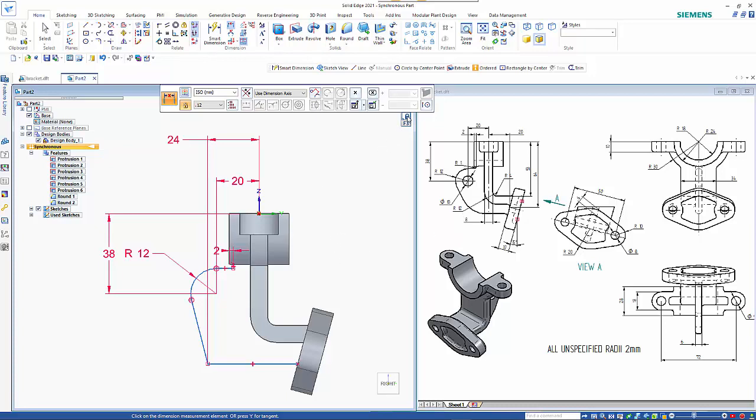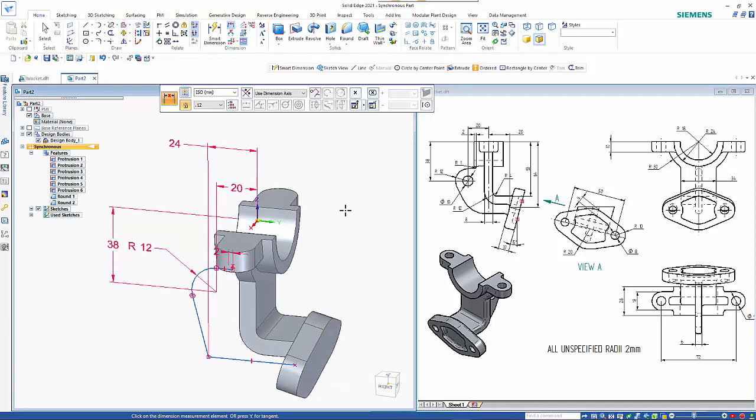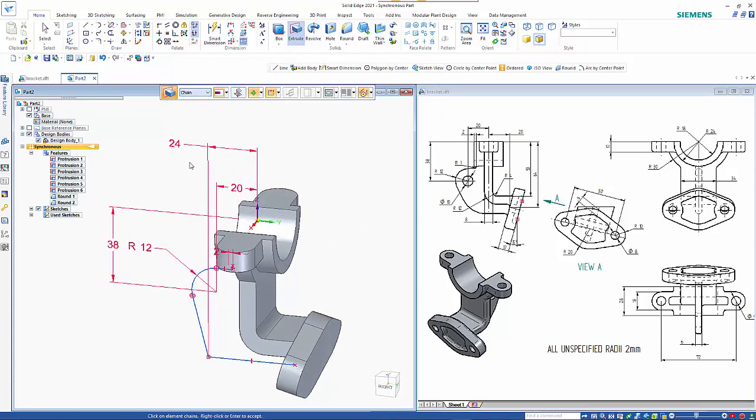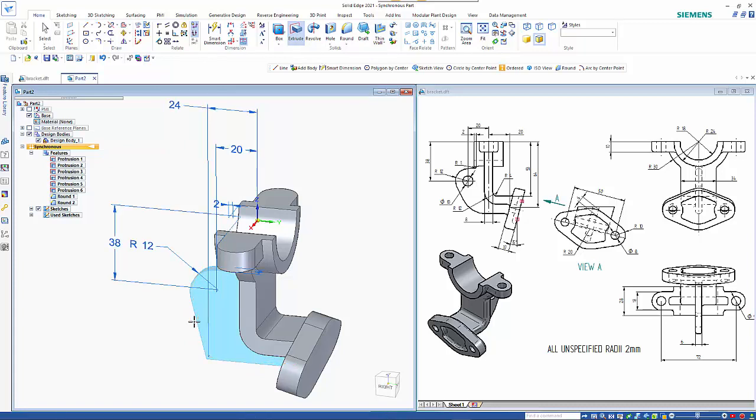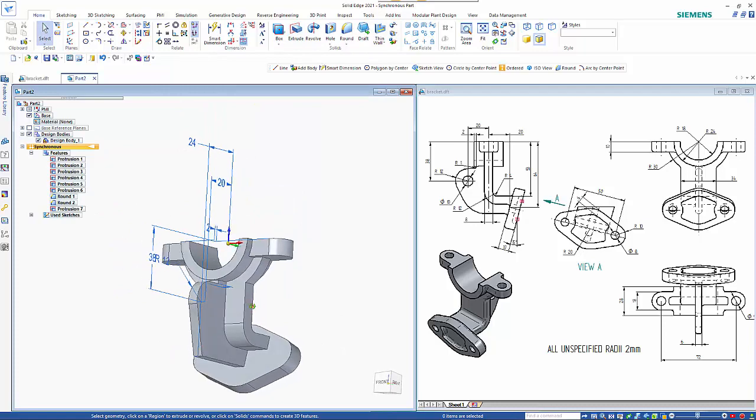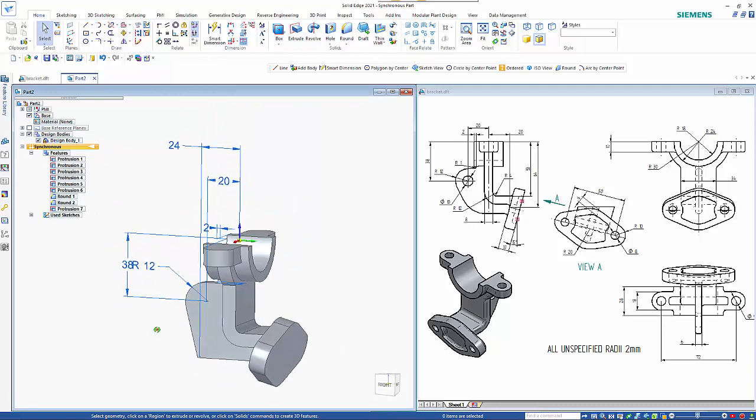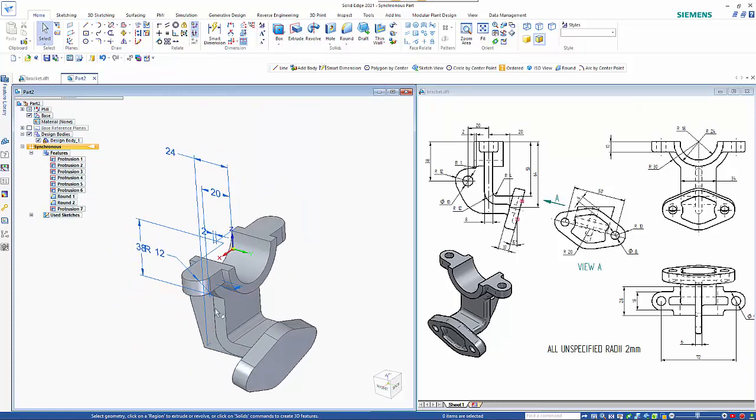So again, we can unlock the plane and use the extrude command, changing it to chain. Inside again, shift key to split it, and this thickness is 6mm. So we just add that in there. So we've now pretty much finished this apart from the rounding.